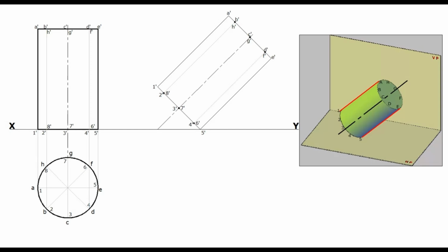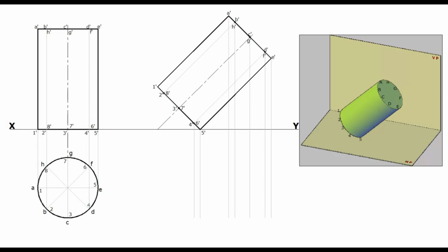Now to draw the plan of the second stage or the final plan, project all the top and bottom base corners of the second stage elevation. Similarly, project all the points of the first stage plan. Trace and identify the corresponding points of intersection in the plan.